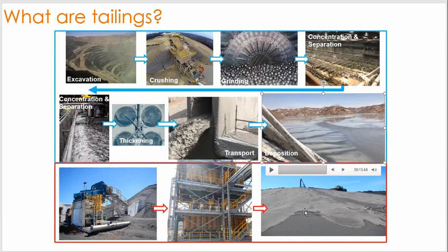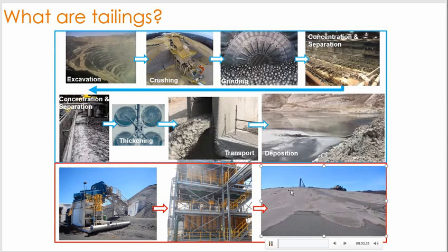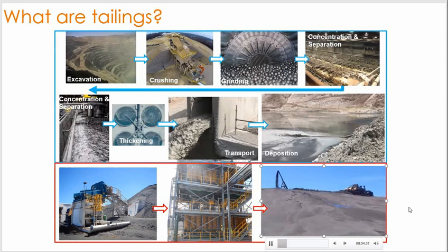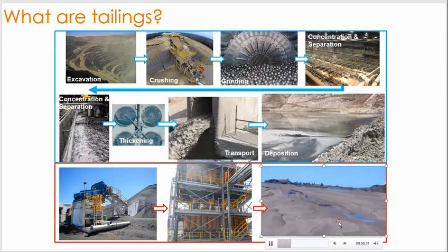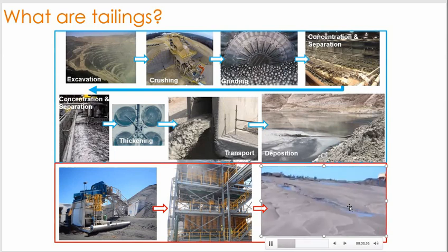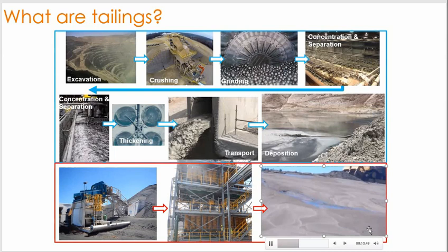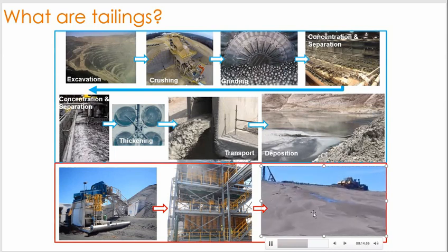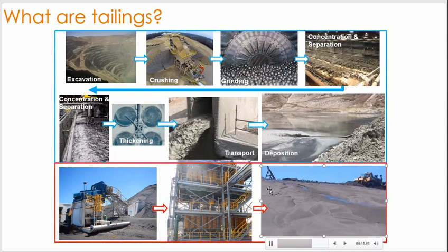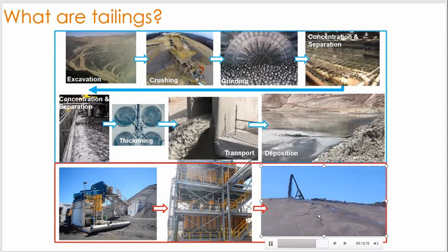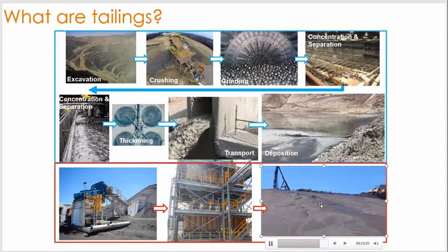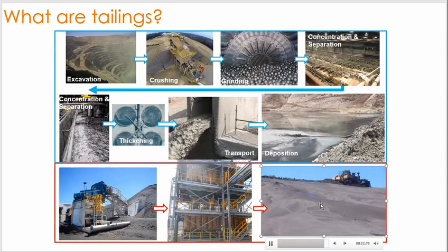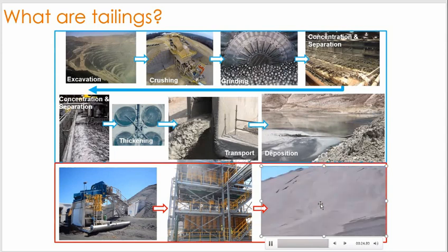your embankment construction material. And it's deposited on the embankment as a slurry, just as it would be in the impoundment. The solid particles are going to settle out, and that water will eventually seep into the embankment. You see this dozer here. Dozers will then push the material out into a constant lift height. The material will be compacted, and the dam will just continue to be raised that way, basically for years on end.